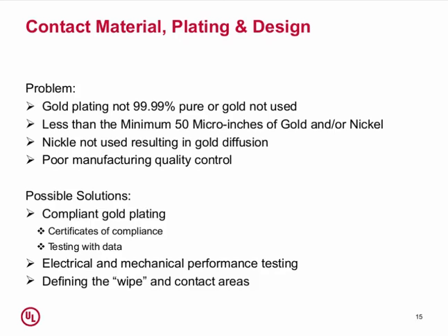Also, defining the wiping contact areas. This is something that's important with modular jacks. Because the price of gold is so high, you don't necessarily want to plate the entire contact area. So what a lot of manufacturers do is they provide gold plating where the contact actually takes place. But obviously that requires some diligence in making sure that the plating is in the area of contacts, that it's not drifting because of bad quality control in the manufacturing process.